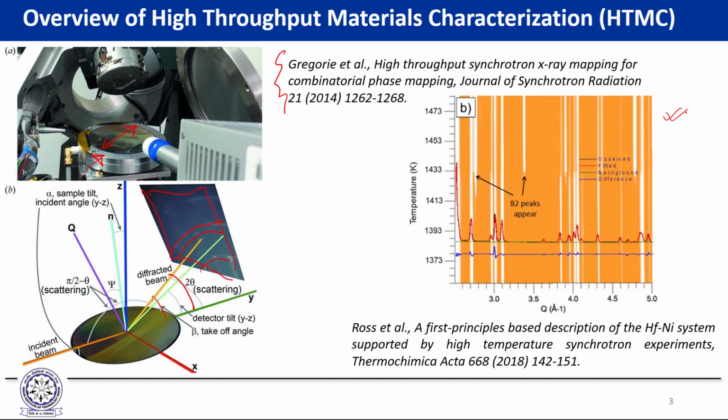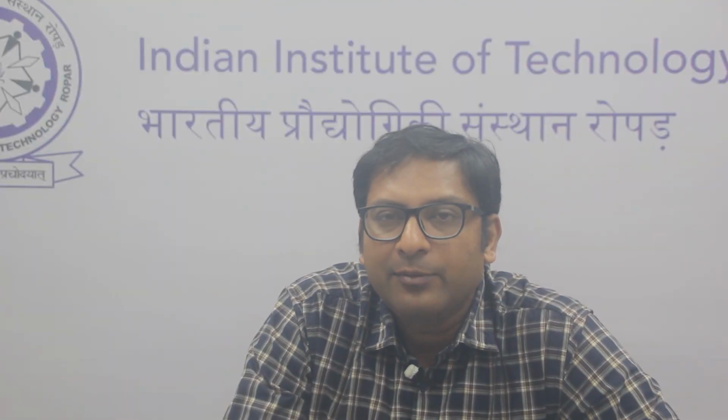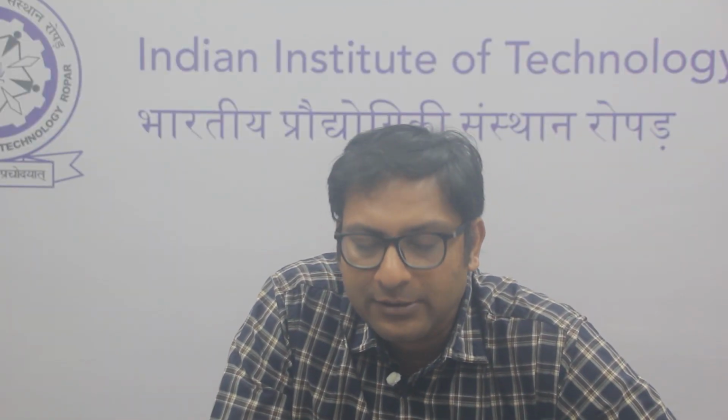Now, if you look at this experiment, on the x-axis we have plotted the values in Q space, and on the y-axis we are plotting the temperature. When you are looking at a peak, the brightness of the peak corresponds to its intensity. What you basically see is that at a certain temperature one set of peaks starts to disappear and another set of peaks starts to appear. So this is really where the hafnium-nickel intermetallic is undergoing a phase transformation.